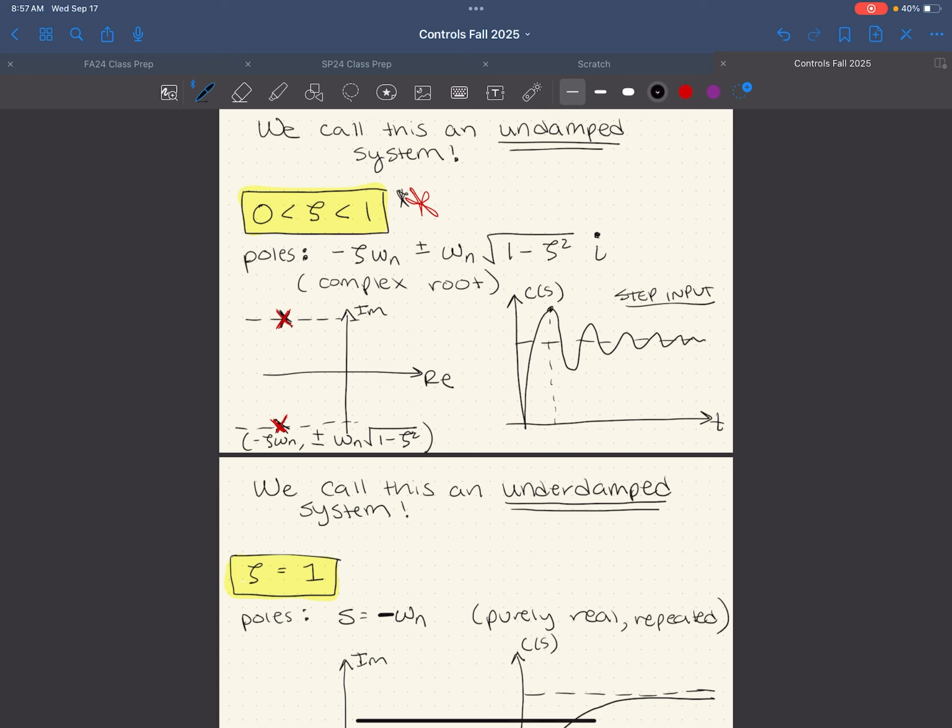So let's say I am a control engineer and my boss tells me, hey, I want you to design a control system with a very specific peak time. When you go to look at your system and decide where you should put your poles on this pole zero map, you should say, okay, I am restricted to placing my poles on this vertical line that achieves my desired peak time.